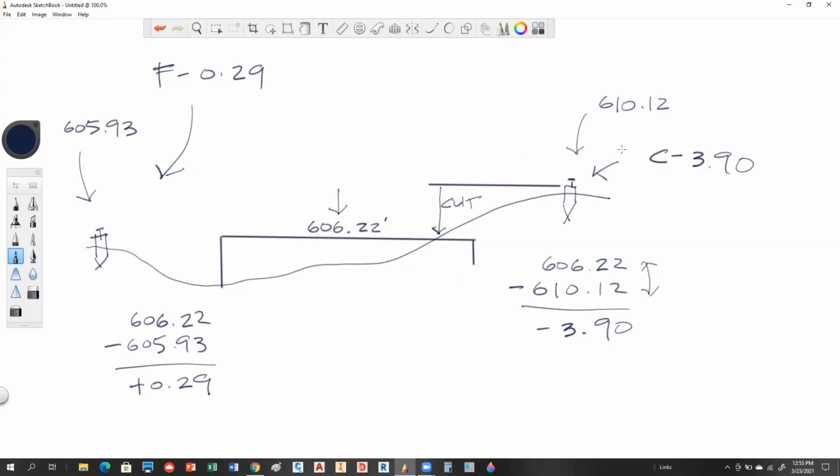Yeah, it does. Probably one of the easiest things you do, guys. Really, if you think about it, there's not much to it. Now, as we start to get into highways and sewers, you're going to have a lot more stakes. That's the only difference. Let me show you a sewer one here in a minute because we're going to talk about some alignment issues. Okay, everybody okay on that? Yep. You'll probably have to do a cut and fill problem, okay? So it's just a matter of getting your elevations of your stakes, knowing what your finished elevation is, and then just determining whether you're above it or below it. That's all you need to think about. Okay.